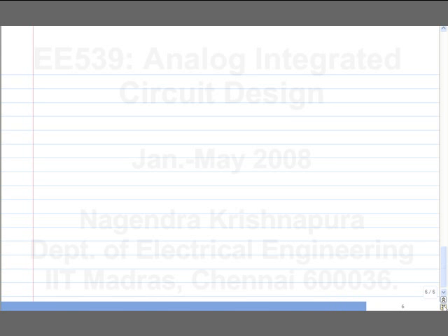And in most cases, you can approximate the two poles to be the input impedance, which is roughly 1 over Gm, divided by the input capacitance, and the load conductance divided by the load capacitance. Now, of course, if you have an open circuit load, this doesn't apply. Then you will have to do something else. And the output pole, or the pole on the load side, tends to be the dominant pole because it's at lower frequencies. Any questions?